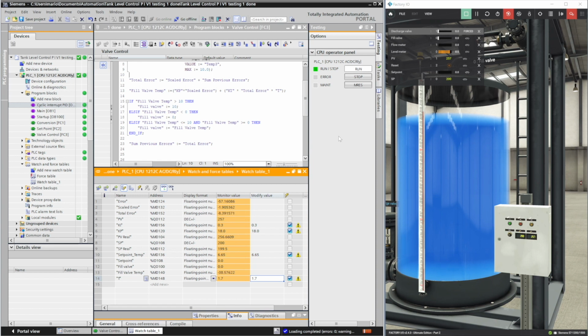If I'd increased Ki to say 0.8 and carried out the same tests, we would have seen not only an increased overshoot, but the tank would have overflowed and we wouldn't have been able to note the actual water levels. Anyway, we'll see this increased overshoot shortly when we increase Ki.